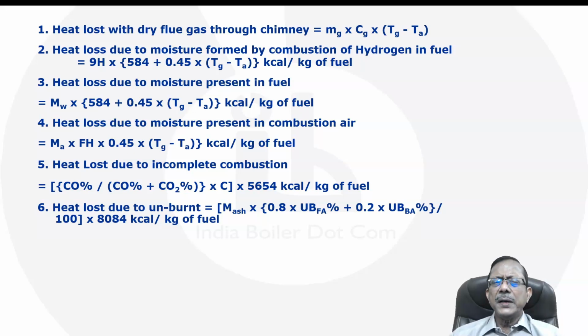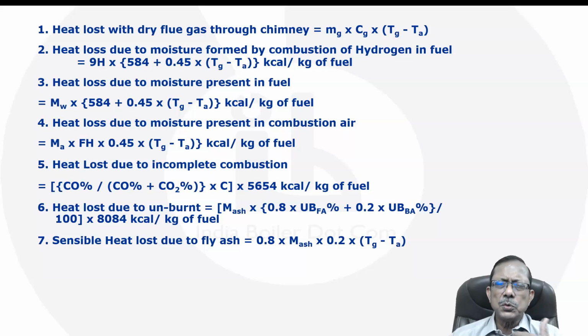Then we can calculate the sensible heat loss due to fly ash, because the fly ash is going at a high temperature, right? So at APH outlet, the temperature of the fly ash should be the same as the APH outlet gas temperature.